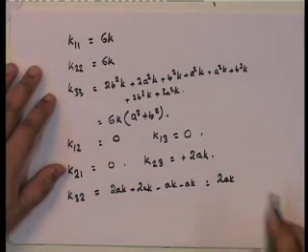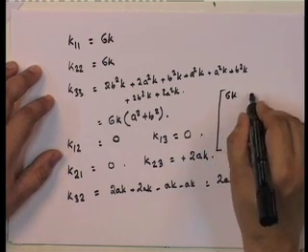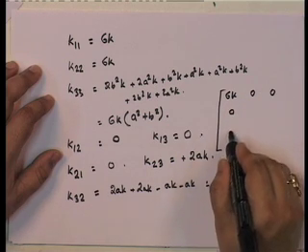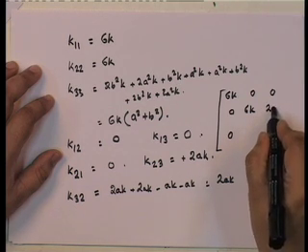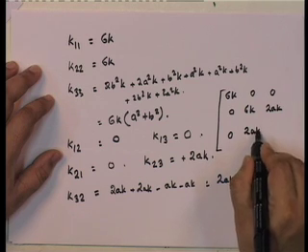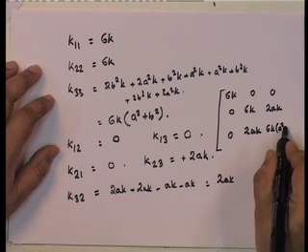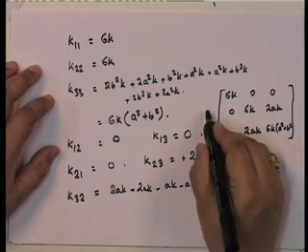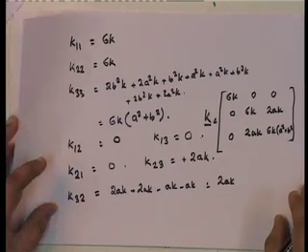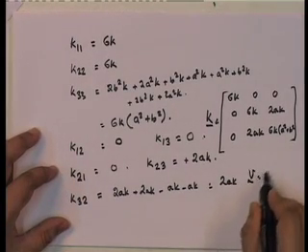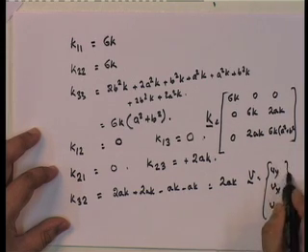So we've got our stiffness matrix, and the stiffness matrix is what? Stiffness matrix looks like this: 6k 0 0, obviously 0 0 here, 6k, okay, 2ak, 2ak, and this one is 6k times a squared plus b squared. That's my stiffness matrix for the degrees of freedom. These are corresponding to vx, sorry, vy, vx, v theta.